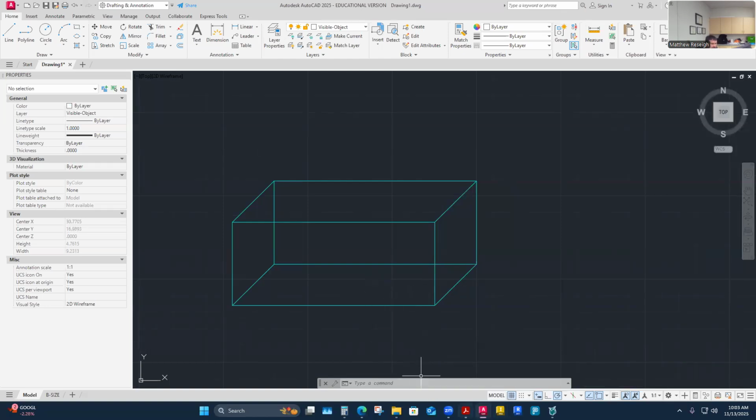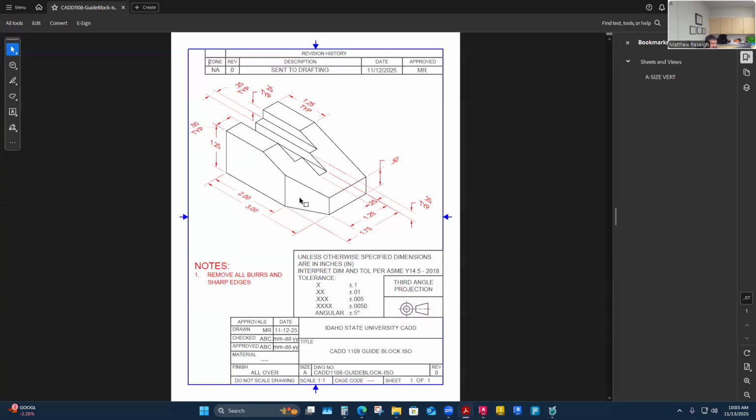There is an angled section of the front view here. It's going to be foreshortened in the front view, but I'm going to put this in actual size right here. So this is going to be full size. So I'm going to draw this first. I'm going to kind of build off from it and piece together what I can, knowing that any depth dimension is going to be essentially half of what it actually is. So any depth dimension is reduced by half. Okay.